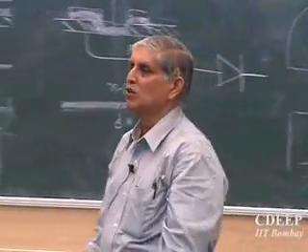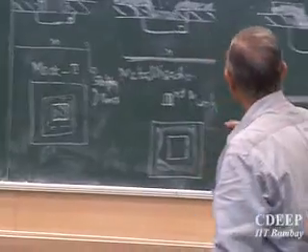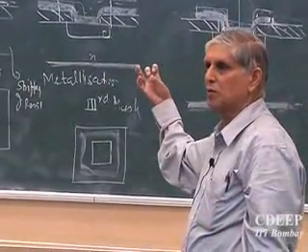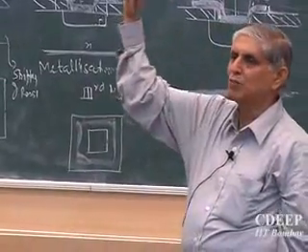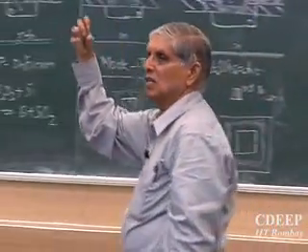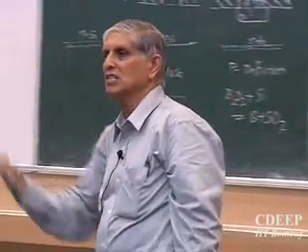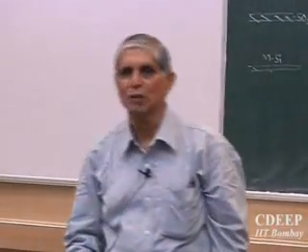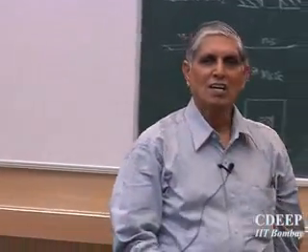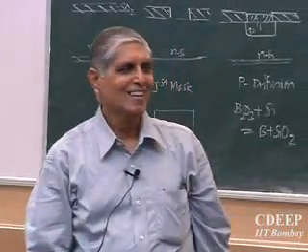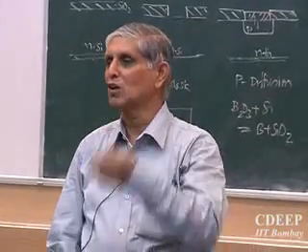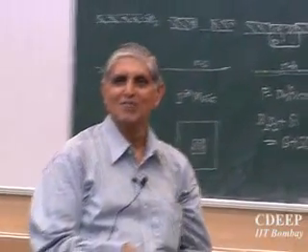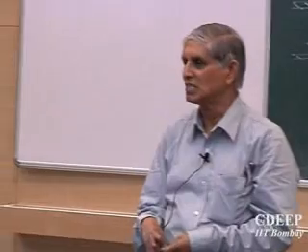So I made a diode using a PN junction, so I can make an NP junction. What should I do for NP? Start with a P substrate and impurity. Which impurity should I use? Phosphorus, in normal cases, or arsenic. Arsenic is much better. Okay, I'm not kidding. There is a word, something called solid solubility. Have you done any course in materials sometime? The word is solid solubility. What is it?